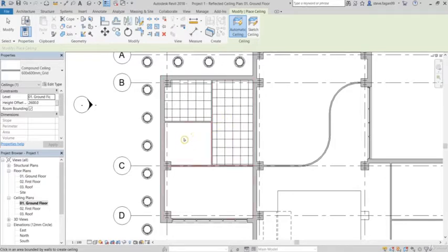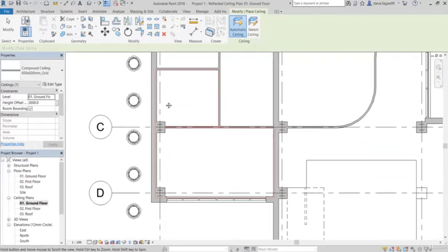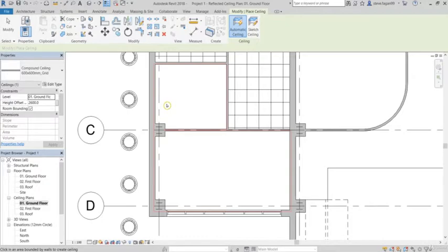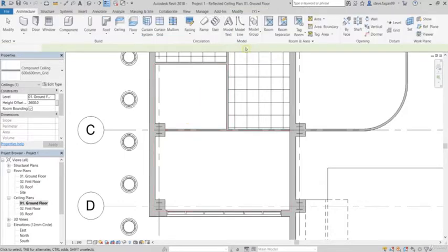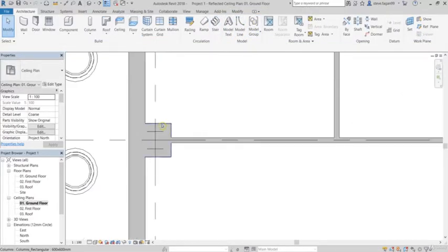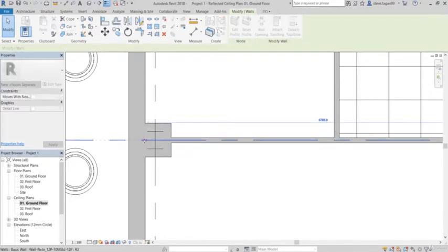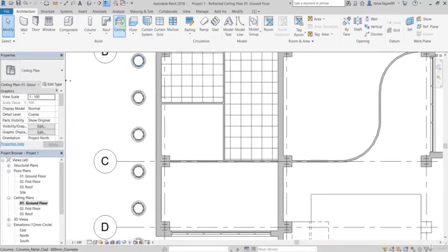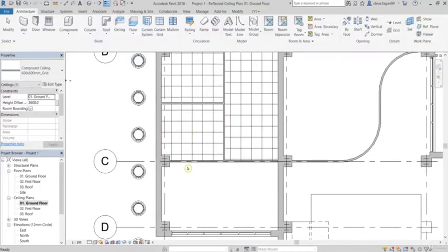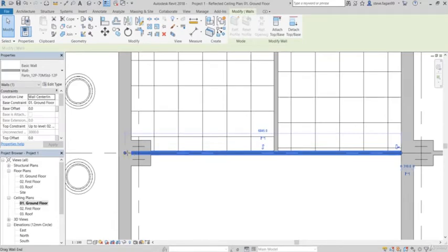If I now go for this small one on the left, you'll see that it's spilling inside the other room. If I zoom in, you'll see the issue is with the architectural column. The red line is running around the inside of the room, and once it gets to the architectural column, it spills into the next room. There's two ways we can get around this. One, we can go to the sketch ceiling, or we can click the partition and pull it over to the external wall. Now when we use our automatic ceiling, we're able to place it. Then afterwards, just pull back that partition.